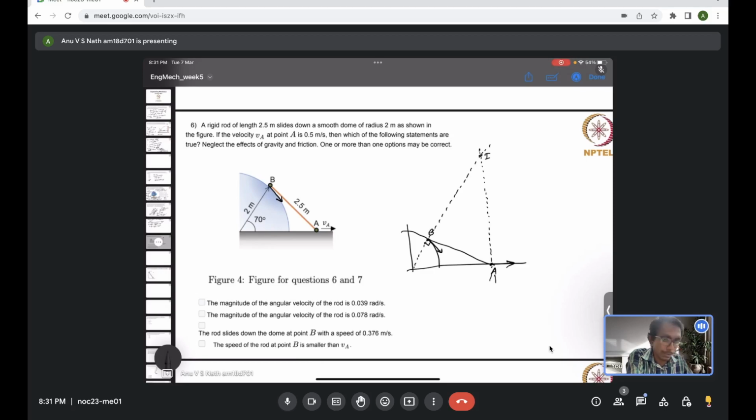This is for the link AB, because we are considering 2 points in the link AB, A and B. We know their direction of velocity. At point A, it should always be parallel to the horizontal line. So we just need to draw the normal to that velocity vector. It should reach the center of rotation, right? At some point, we don't know, right? Let it extend to infinity.